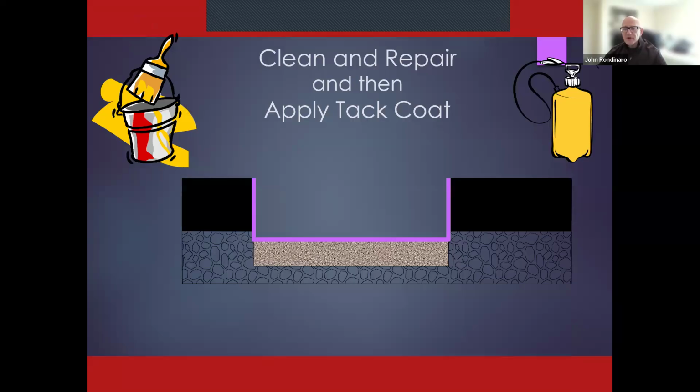And this is going back to our question about the patching, or a question about sealing around that edge. What's going to help you a lot is you've got to get the tack coat in here, and it is something that a lot of people still don't do.